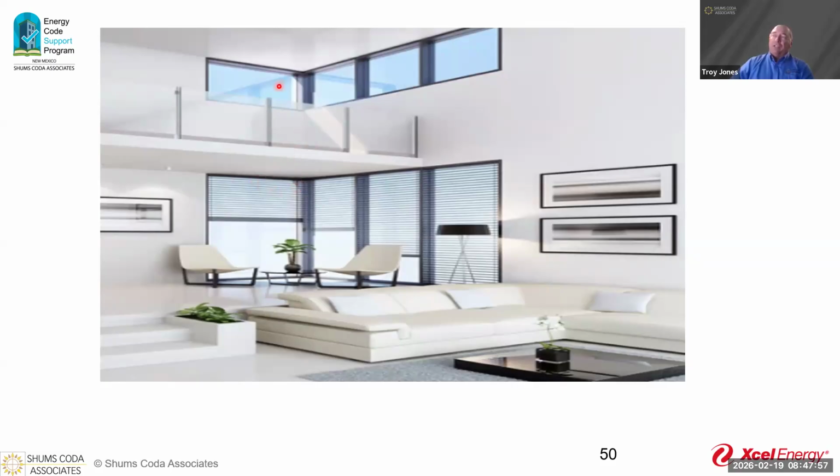Where it becomes interesting is because we have these monitors up here. The second part of this question, which I'll answer, is do we need to have two sets of daylight zones? Because we have this here, it's all under control, so that's a ceiling height there for those primary zones coming out here. Yes, that is correct. We would need two different daylight zones because of these upper monitor windows.